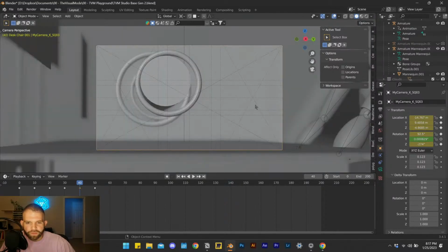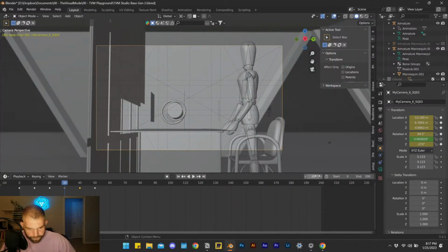If I click here to go back into that camera shot, just kidding, I think it might have been keyframe 30. I could also just go back in my storyboard to check. Yep, there we go, where he stood up. And we're going to end up moving this camera slightly back for this new shot, but I can build off of this one. So we're on keyframe 30. Instead of copying these values over the long way, I'm just going to hit Shift D so I can copy all those settings on that keyframe for the camera over to frame 60.